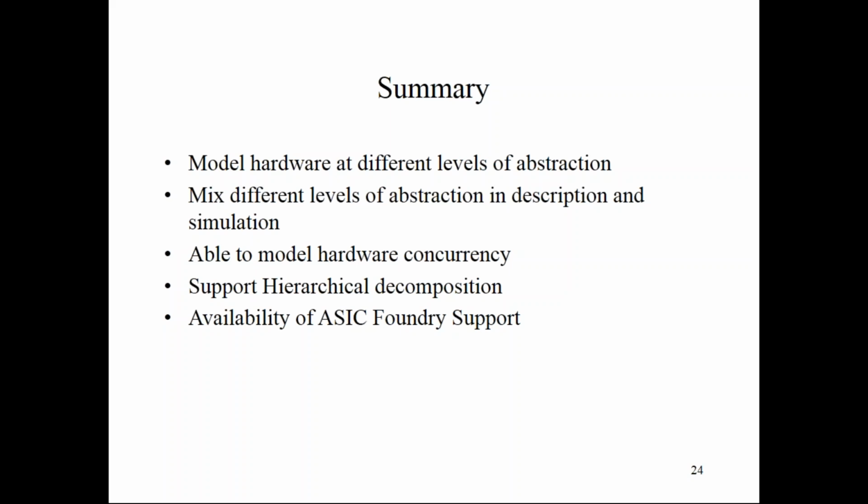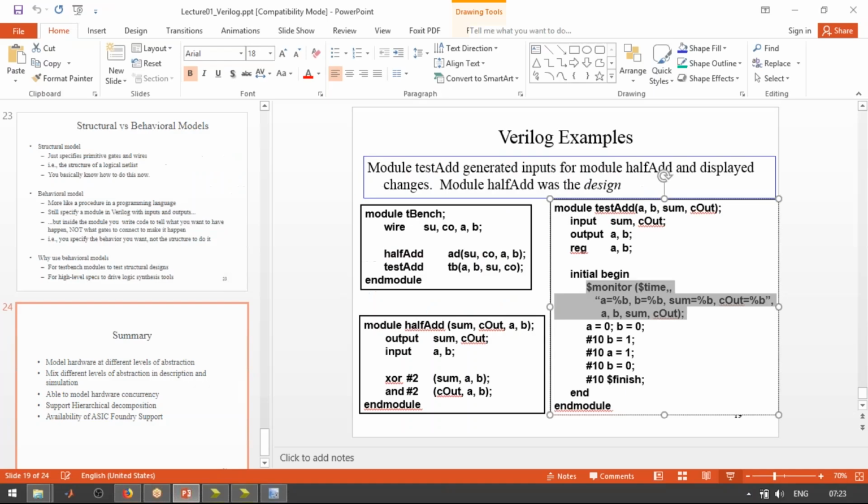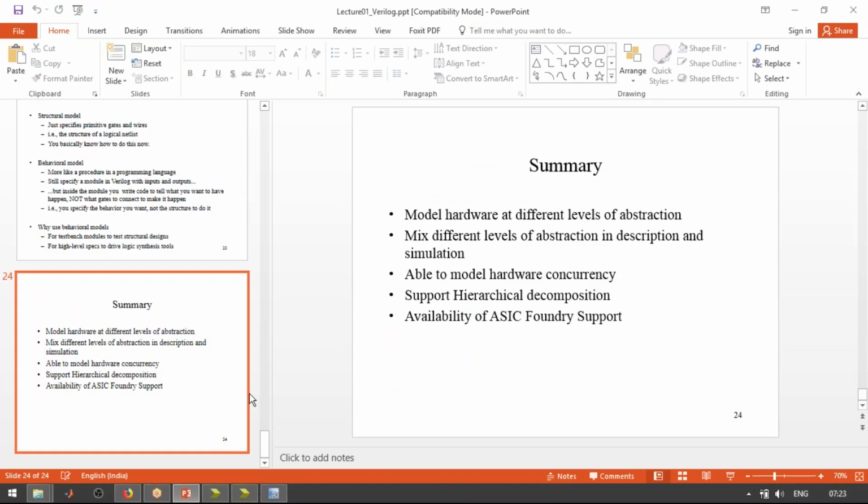From that we are getting the actual GDS2 file after place and route and floor planning. After doing all those steps, we generate the GDS2 file. If we give that GDS2 file to the foundry, we get our hardware module for fabrication. So the GDS2 file is made after layout, and that we give to the foundry.